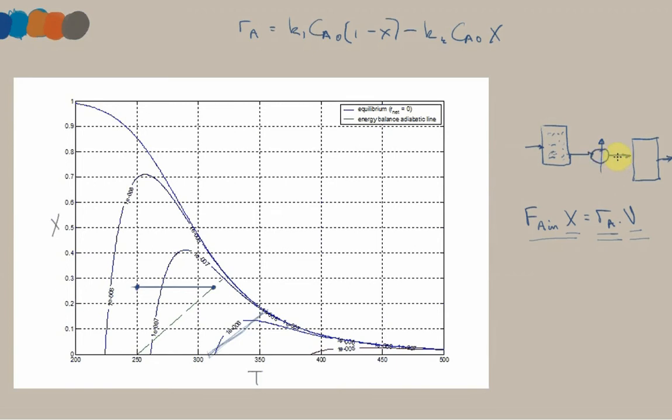So basically we can design this heat exchanger such that we achieve a reduction in temperature here, like so. So we've restored the entry temperature here to 250. So we have a 250 here, we had a 250 here, and we have, let's say, a 320. So we entered the reactor at 250.